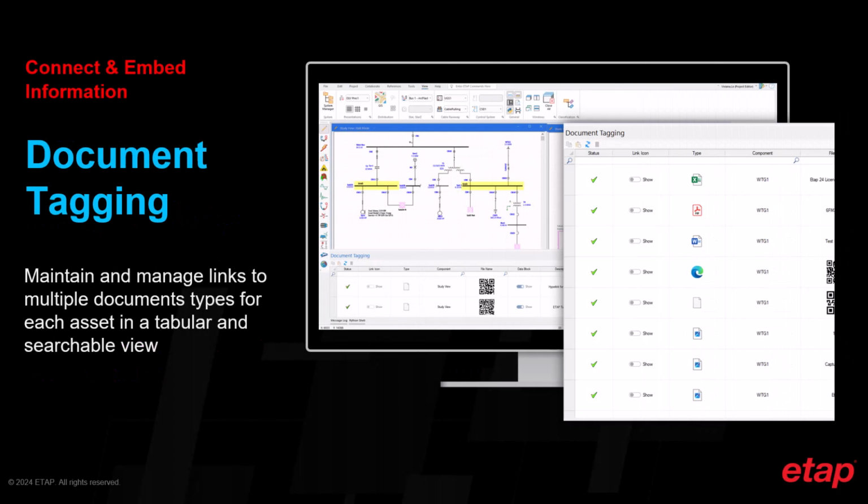Another way to connect and embed information is through the new document tagging pane. This window provides a means to easily add, edit, and preview diagram and component hyperlinks. Some common applications include linking PDFs or OEM catalogs or operation manuals, viewing equipment photos captured and merged from ETAP app, as well as associating reference reports or drawings. Let's switch over to ETAP and take a closer look.